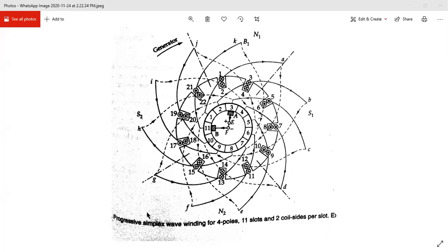Are you getting? Sir, in some places they have shown 11 and 6 connected together. Can that be done? Yes, they have connected 11 and 6 together. Ultimately, you put the brush and then the common connection avoids the coil, so there is no need for it. So if you short these 11 and 6, then this total whole coil will be bypassed. That will be clear from that diagram you are telling about. Did you understand? Yes sir.